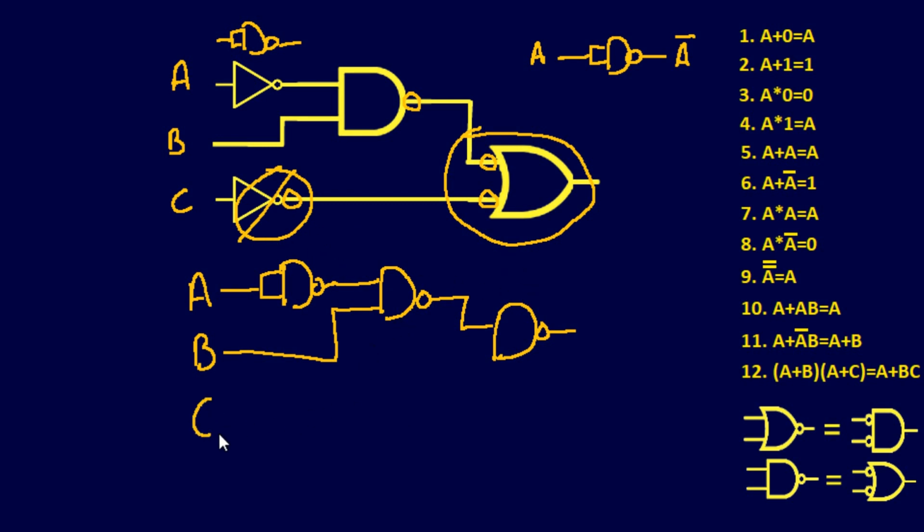So we actually have a 3-gate setup here. So we're actually only using one chip right here, one 7400 chip, and we're only using 3 gates. Very little work. Whereas this one used one chip for just one gate, this used a different chip for another gate, and a 3rd chip for just 2 NOTs, or 2 inverters. So this is a little excessive for just a simple little 3-gate system here. So we just used one 7400 chip and 3 NANDs just to make this simple circuit.